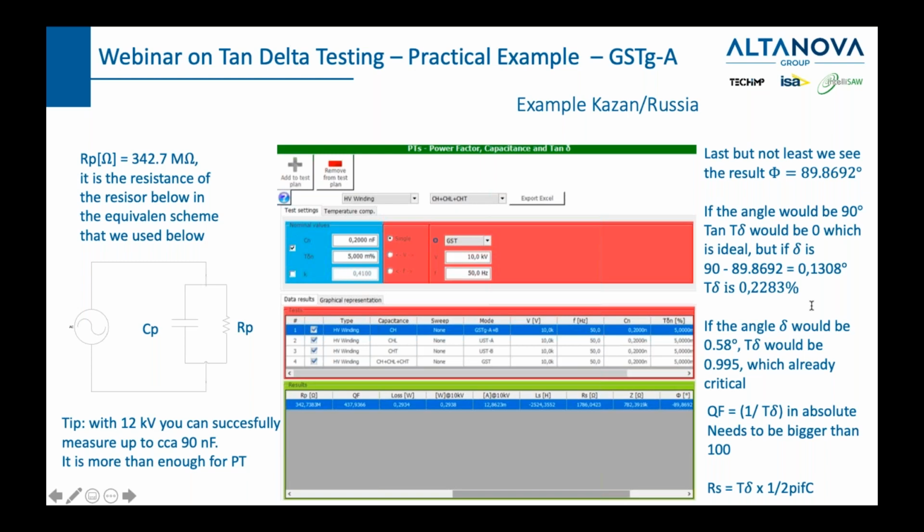So that is possible, because when we are testing on generators and motors, we need more than 300 milliamps. Sometimes we need 1 or 2 or 4 amps, and then there is a reactor, which is basically the winding, the inductance, which takes over, which creates, together with the capacitance of a rotary machine, a resonant circuit, and then you can generate a bigger current.